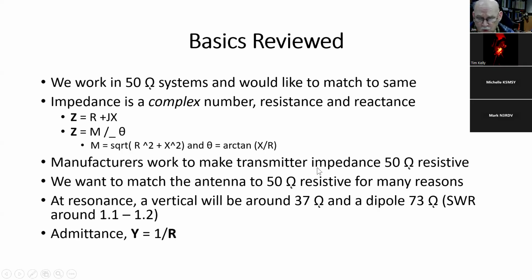The manufacturers work to make the transmitter impedance 50 ohms resistive. And with solid state devices, the way they match those things, it's very broadband, as opposed to my SB220, which I have to tune if I move 200 kilohertz on 75 meters. But most of us are running solid state radios, which the manufacturers have designed for 50 ohms. That means the transmitter wants the antenna to be 50 ohms, and that's not always the case.